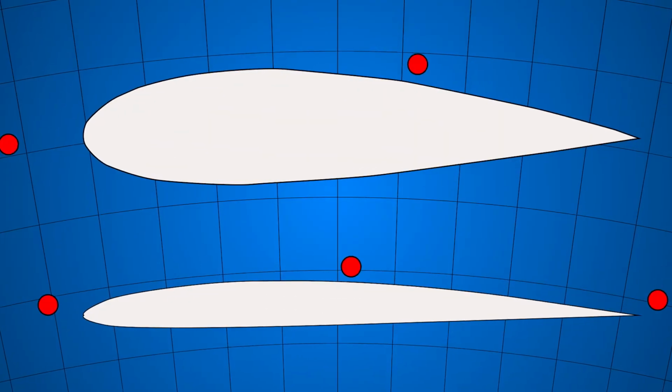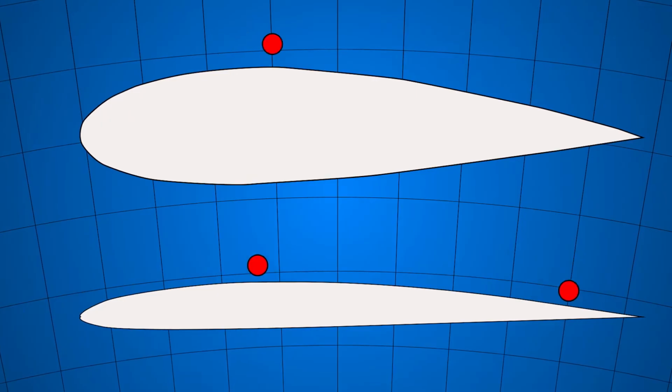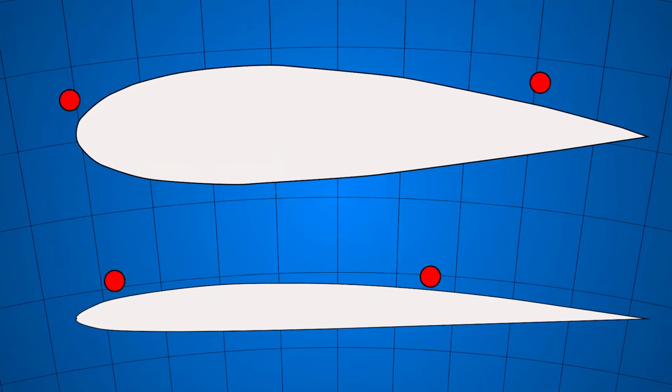If you already knew about swept wings, there's likely another explanation you're aware of. Look, before realizing that angling the wings helped with the wave issue with what happens above the wing, they simply reduced the thickness of the airfoil to be used. Because the thicker the airfoil, the faster the air has to go to get around the top. The thicker the material, the less it affects the air. This example makes it easy to understand.